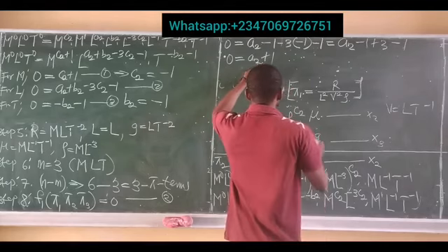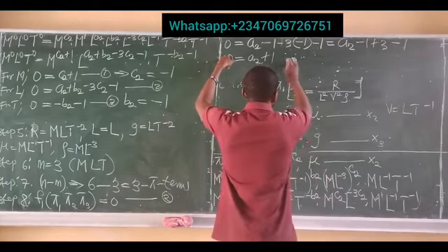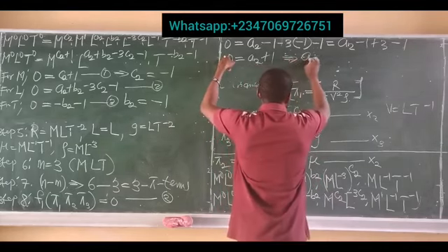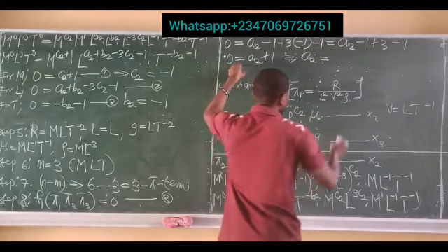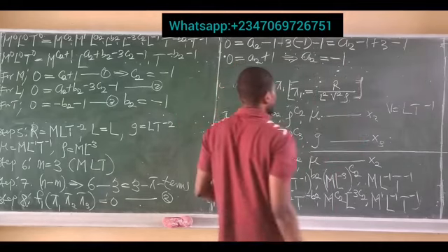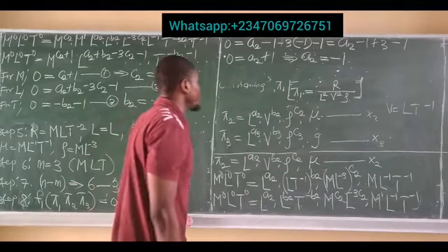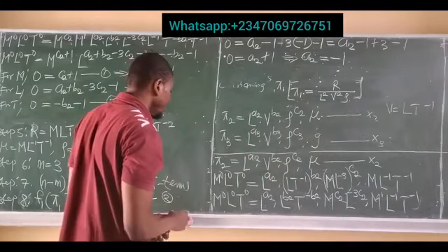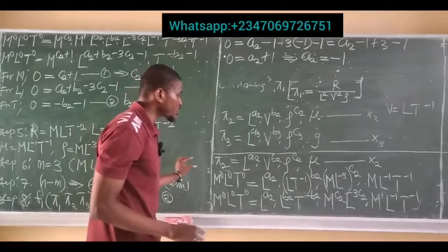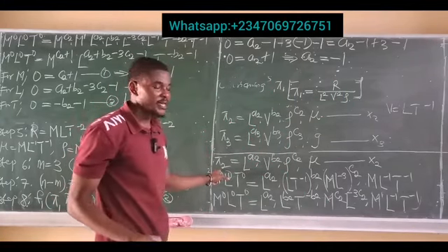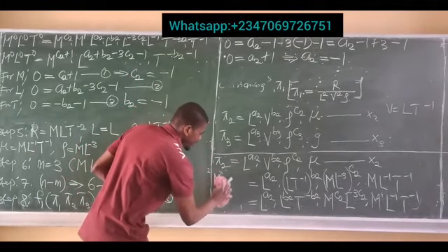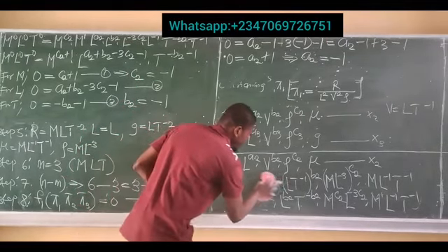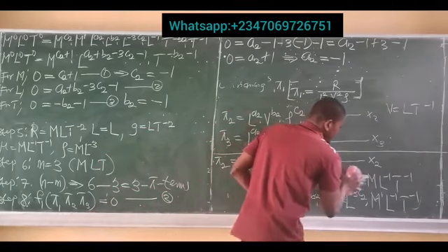So to make A2 subject, simply send plus 1 over here. This implies now that A2 is equal to, when positive sign cross an equal to sign, it becomes negative, I have A2 to be minus 1. So we found A2, we found B2, and we found C2. We can now plug it back into the original equation for what? Pi 2, just like we did in the first case. So I'm going to wipe this side off now to obtain the value of pi 2.